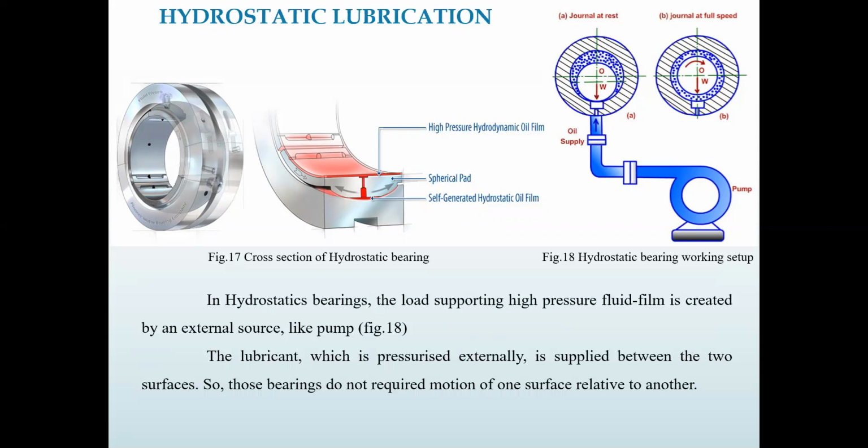The lubricant is pressurized externally and supplied between two surfaces so that the bearings do not require the motion of one surface relative to another, which is, we can say, hydrodynamic action, which is not required in this case.